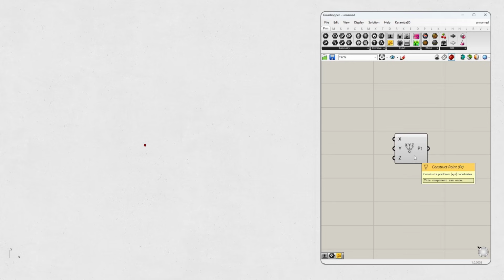All right, so let's figure out these coordinates. For this, we don't even need to pick anything from the menus. All we have to do is double click on the screen, then type in any number you fancy and hit enter. Boom. Grasshopper automatically creates a number slider for that number. After that, it's just a matter of grabbing that slider with your mouse and connecting it to the X, Y, and Z inputs.